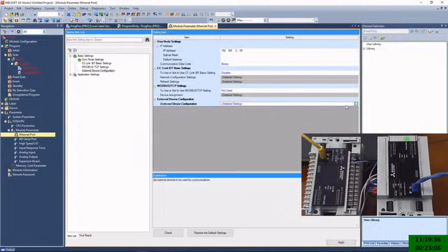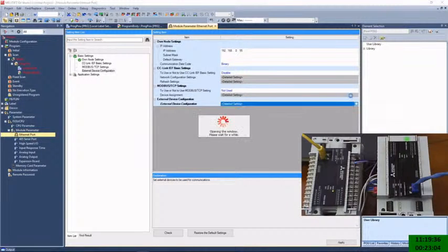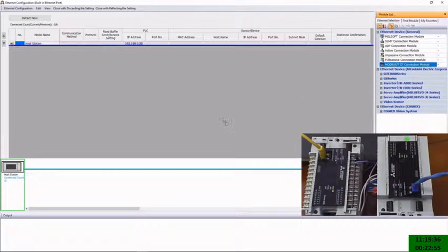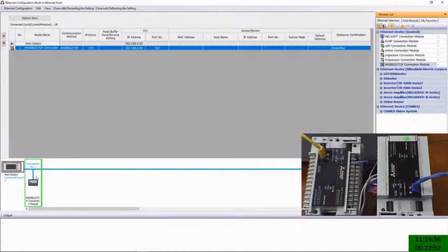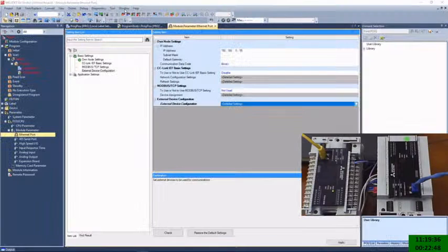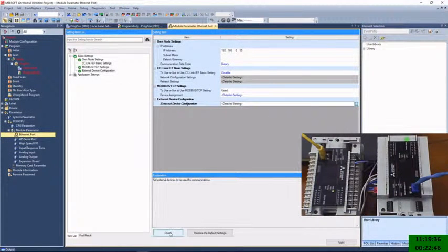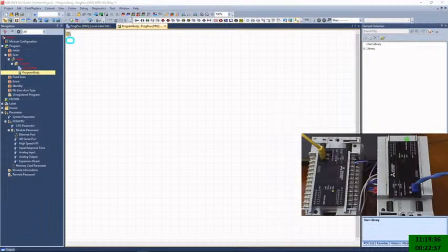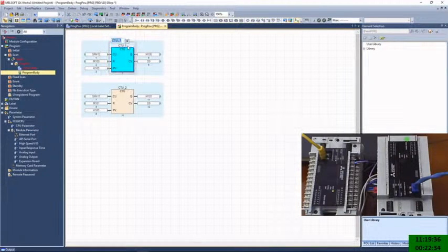And then you go to external configuration again as well. And once you're in there, you will add, like I said earlier, your Modbus-TCP, you're going to add your Modbus connection. So you're basically opening up that connection for a Modbus connection now. Close with reflect, and then you say check, and everything's fine. And exit. What I did is I added a quick little program in here. So there's the little program.